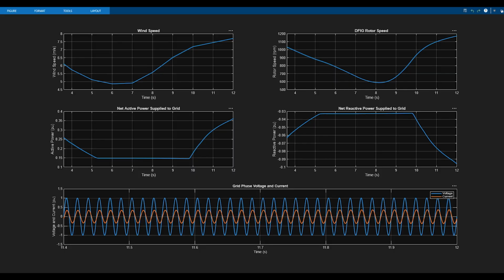Lastly, the bottom right graph highlights that the net reactive power is absorbing from the grid rather than supplying reactive power due to a high inductance value. By decreasing the mutual inductance value, we can get closer and closer to a net neutral 0 pu or supplying. Higher wind values could also help this case by having the wind turbine operate closer and closer to peak power production, as it will yield the best efficiency comparing the base value power versus actual power supplied to the grid.